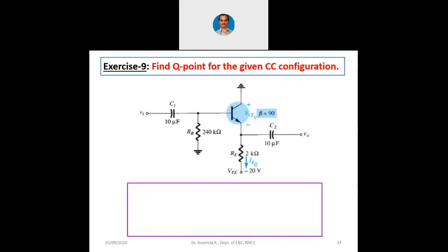Please remember that. We define the quiescent point or Q point as the point at which the transistor is half on and half off. It is exactly at the middle of the active region. So, we are taking output at the emitter now. It does not mean that now the Q point coordinates will change, because again it is between collector and emitter only.